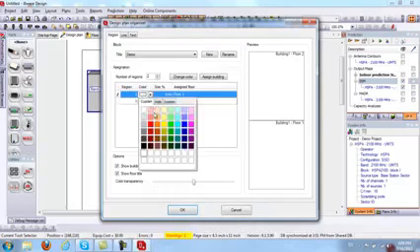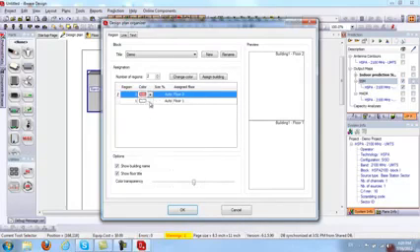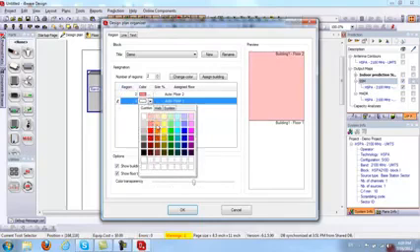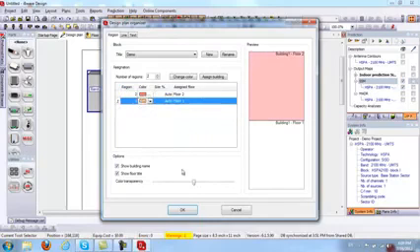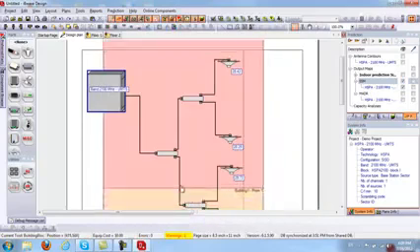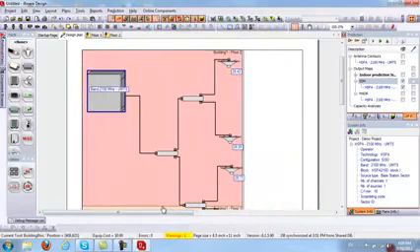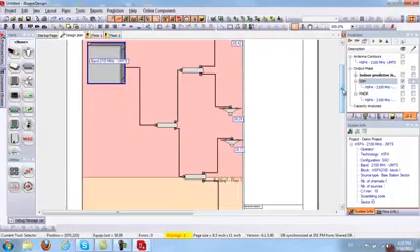And here you can choose different colors for your design plan organizer. So just to differentiate between the floors, once you do that, you can click OK, and this is your design plan organizer. You can put it where you want. You can also right click on it, unlock it, so that way it won't move. Once you do that, notice that we have an option here.